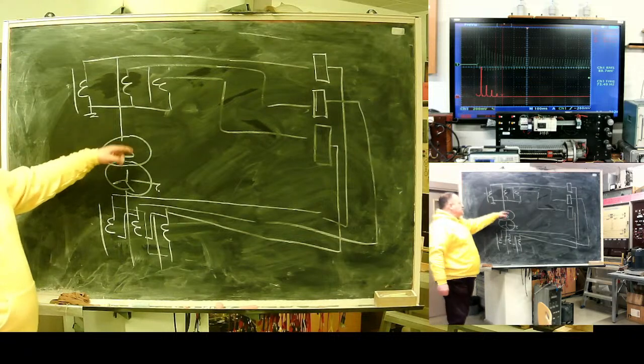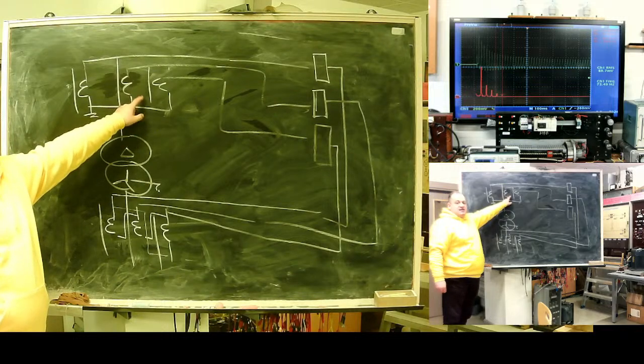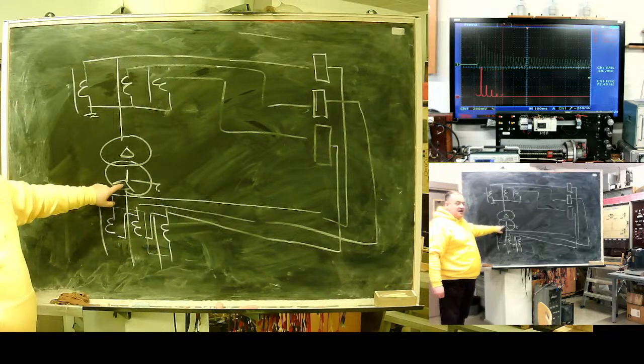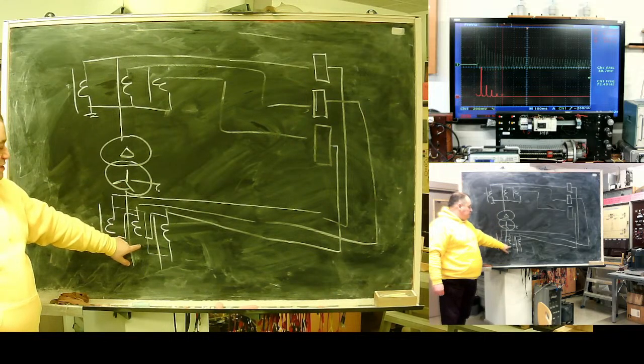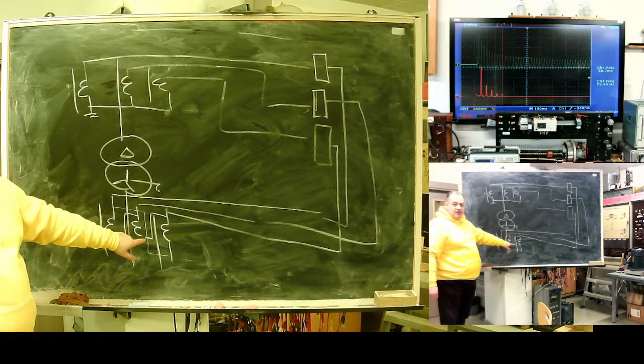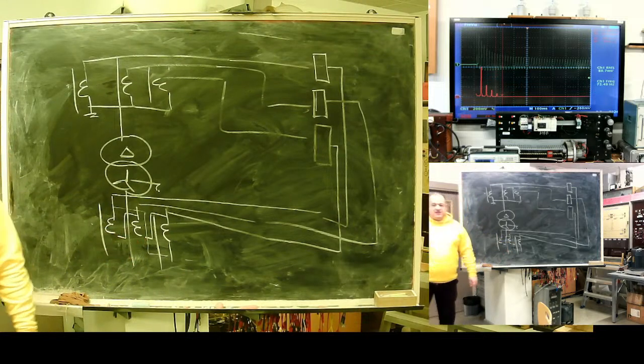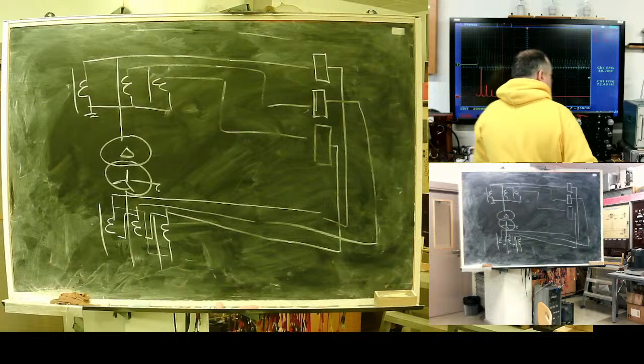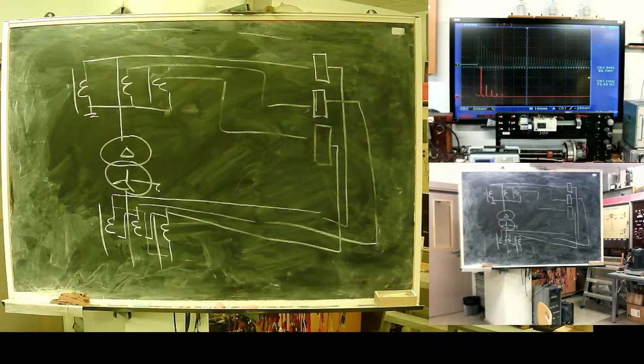On the delta side, current transformers are assembled as a normal star, but on the star side of the primary transformer, current transformers are assembled in delta. Offset system, this compensates the phase shift of the transformer. That's not all.